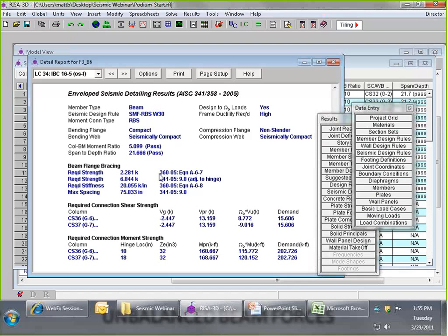about 2 kips per the AISC 360, but per the AISC 341, right adjacent to the plastic hinge, that is where our reduced beam section is occurring, we're going to need to have a brace that can handle up to almost 7 kips of axial force. And so we may actually need to come in with a single angle kicker or something along those lines to get that braced.